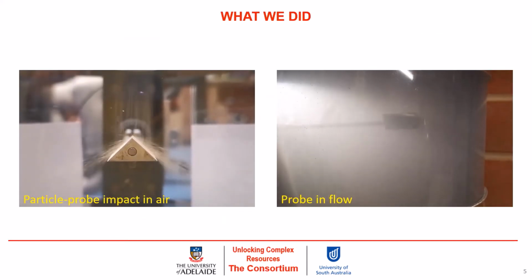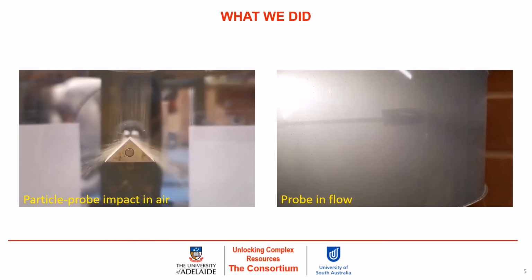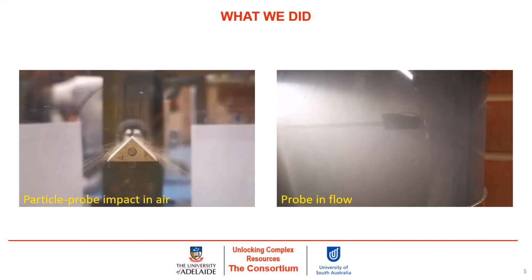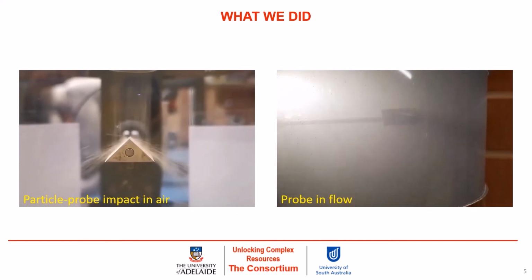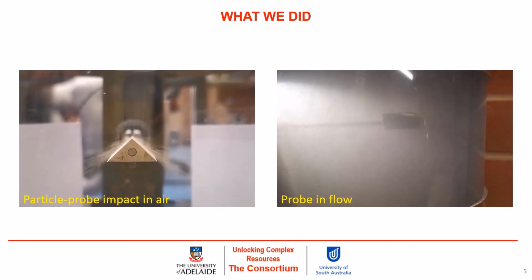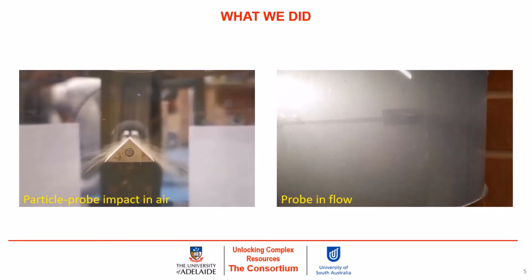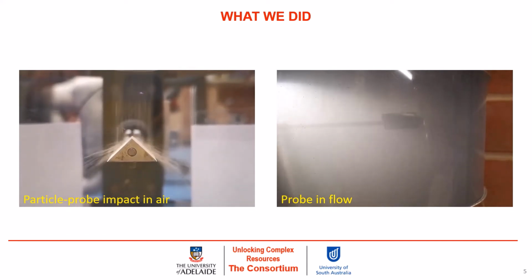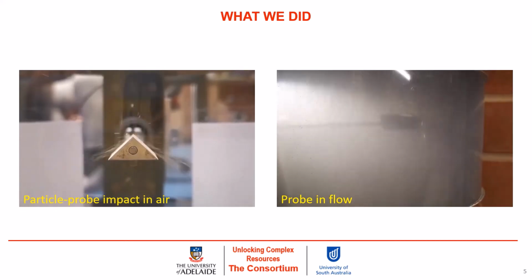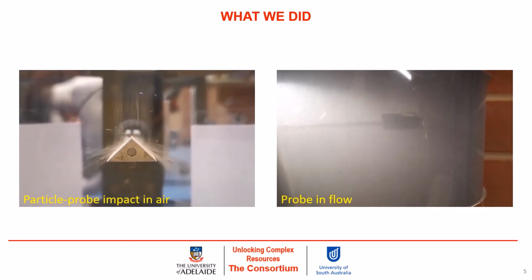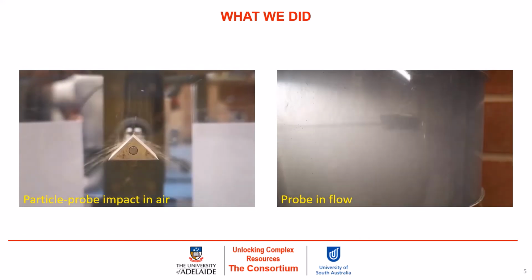To study particle probe impact mechanisms, we have done dry tests in the air using sand particles in free fall from a certain height. We have also put the probe in slurry flow to investigate flow-induced drag and the combined effects with particle probe impact events. In these tests, we have considered more complicated scenarios involving the presence of air bubbles, turbulence, different solid concentrations, etc.